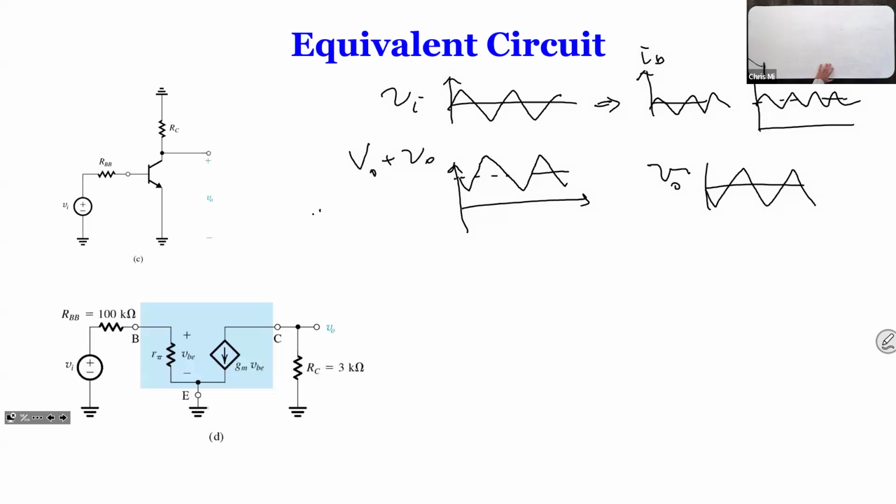Another point to note is that if you look at VO that I drew over here, the capital VO plus lowercase vo is the DC plus AC. For that one, you can hit the boundary. That's your output range. So your bottom output cannot reach below how much? You guys remember? 0.3 volts. And your upper range cannot reach how much? Ideally it's VDD, but it's going to be slightly less than VDD, but we'll temporarily put VDD over there.